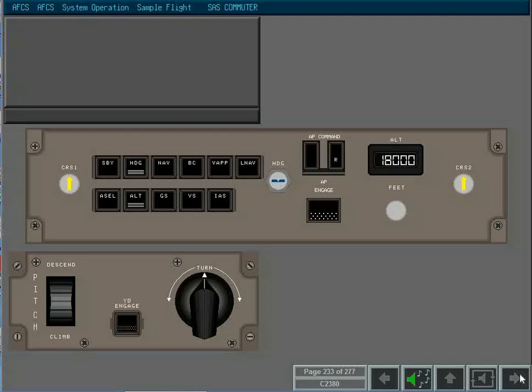To commence descent, select an approach altitude of 2,400 and ARM ACL mode. Then initiate a vertical speed descent at 1,500 feet per minute. Commence descent. When the indicated airspeed has increased to 215 knots, you should select IAS and reduce power to about 35% torque. Select IAS. That's right.